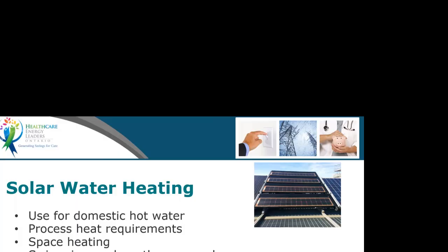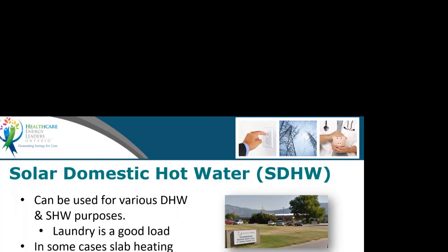And part of doing this effectively is then having places to put these collectors on the exterior surface of the building, right? And the color, the wall surface. So we'll talk a little bit later on about air heaters, but in air heaters, the color is important as well. So I have an example here of the Summerland Memorial Health Center out in BC, where they basically used solar hot water to provide for domestic hot water and in the laundry. It was a good load.